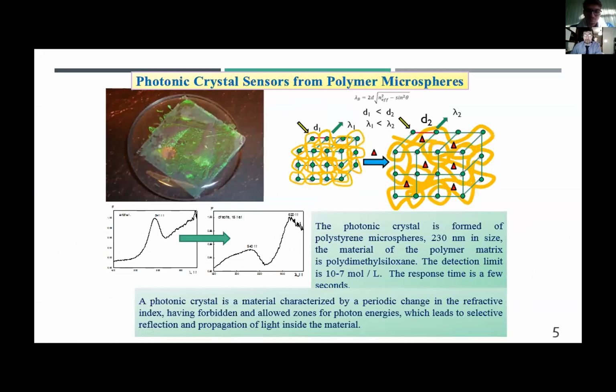To do this, a drop of suspension containing the optimal content of the dispersed phase and the required amount of the surfactant, which was sodium dodecyl sulfate, was applied to a clean, dust-free polycarbonate substrate of specified dimensions. After that, the sample was placed in a preheated drying oven with forced convection. The surface on which the future sample was located was massive and decoupled from the main cabinet structure to reduce the effects of external vibrations produced mainly by the fan rotor inside the cabinet itself.